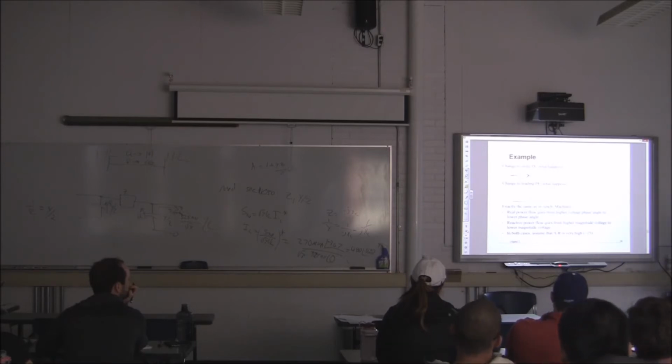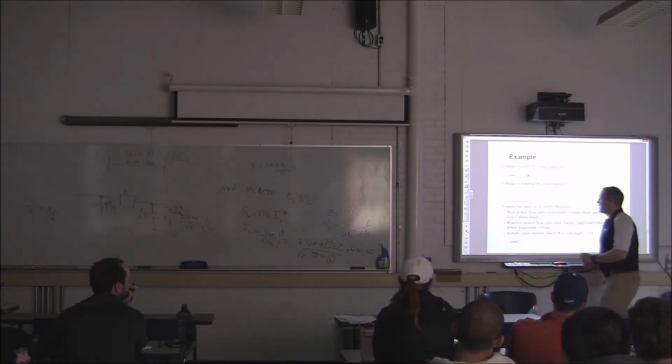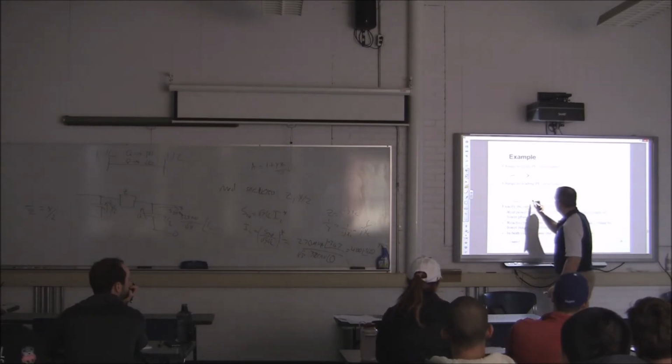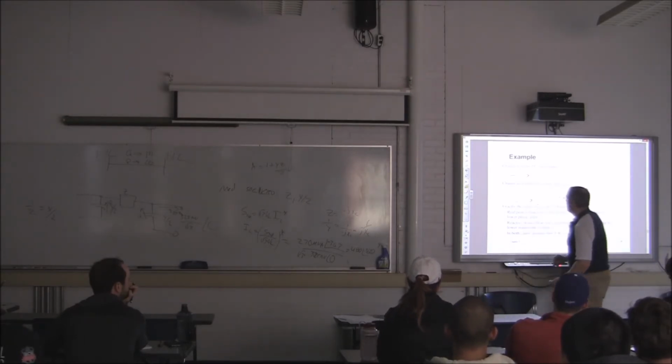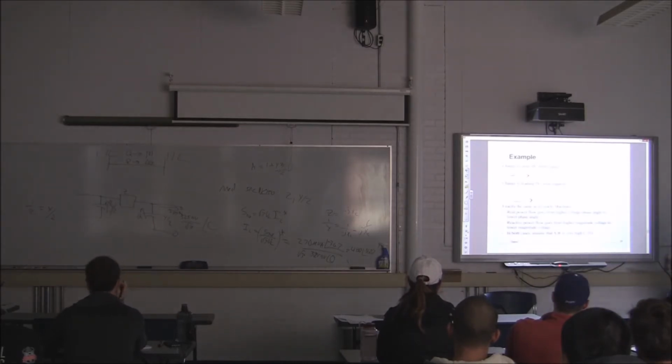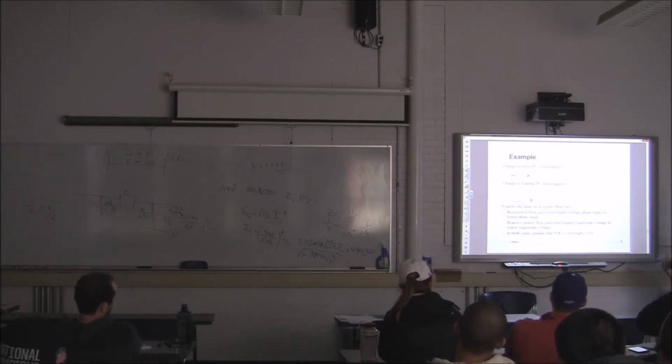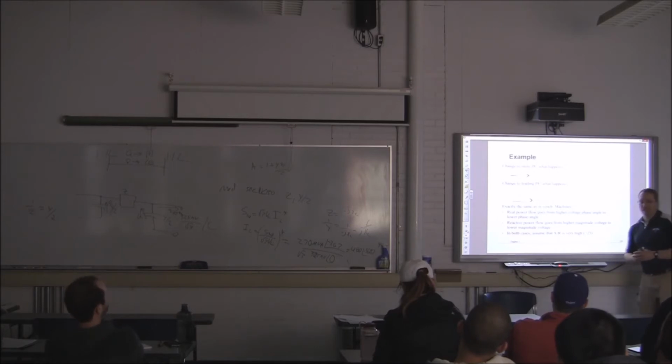Is this a leading power factor condition? Let me draw the IR here. Would you agree that this is a leading power factor? Yes. Okay. So what happened to the magnitude of Vs? Is it less than or greater than Vr?